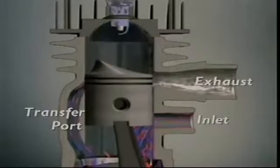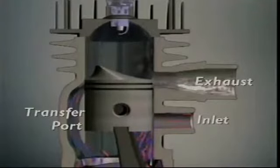downward. The piston moves down. The bottom of the piston covers the inlet port as the top of the piston uncovers the exhaust port. Opening the exhaust port starts the scavenging process. It releases the pressure above the piston and burned gases escape.